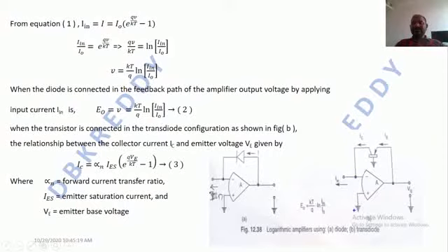So how much voltage is there at the non-inverting terminal? It is ground. So this ground voltage is there over here. If you see this one, it is not indicated that the base and collector terminals are shorted, but actually they are shorted. How much voltage is there at the collector? The same voltage is there at the base terminal, means it is ground only. So the collector is connected to the ground, the base is also connected to the ground, obviously it is shorted. So this diode is acting as a trans diode.